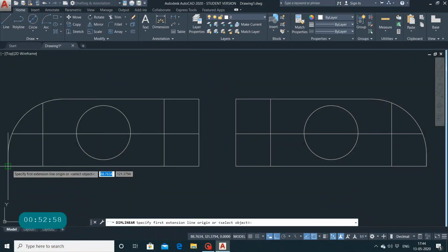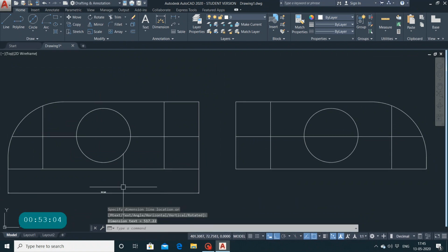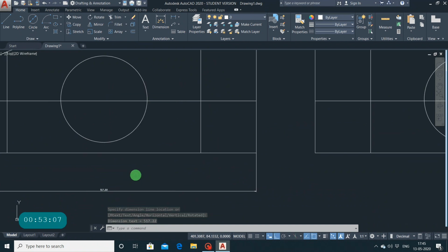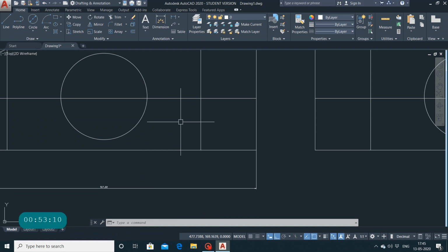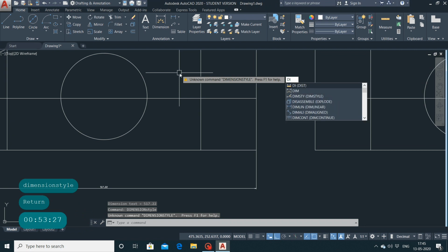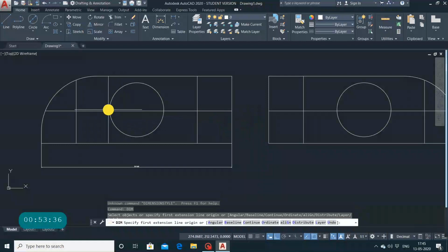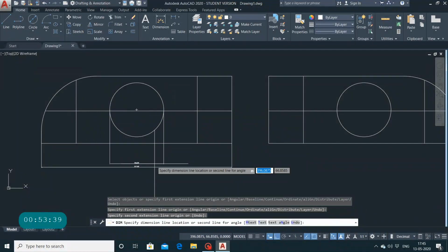How would you change the size of the dimension? We'll go to annotation, standard ISO 25 annotation. You can click on this annotation just to remove it, unpin. So these are all the dimensions. Escape. These are all the dimensions.